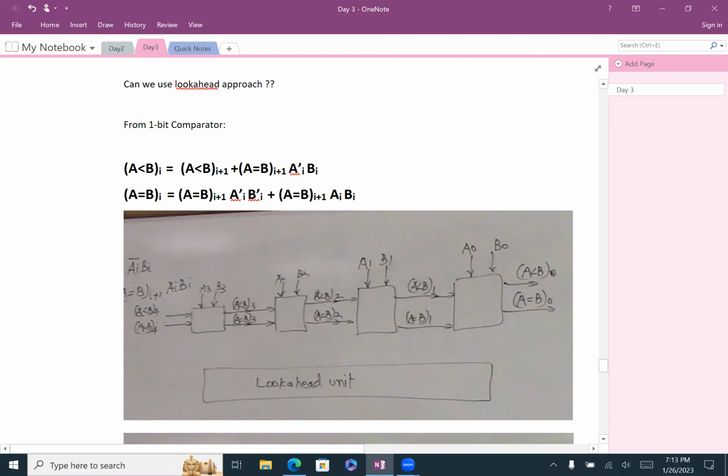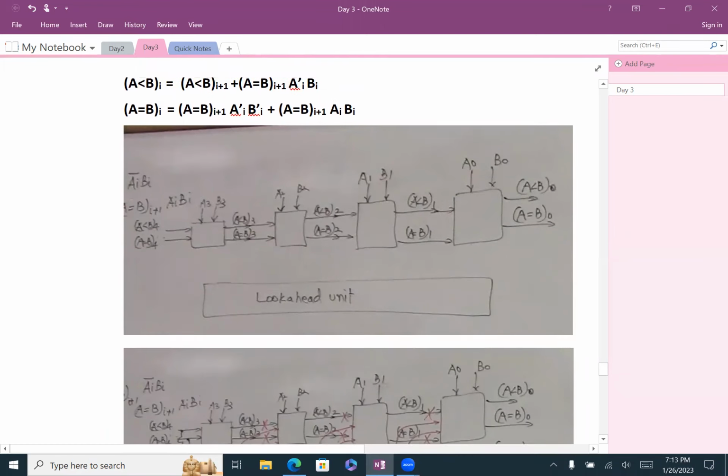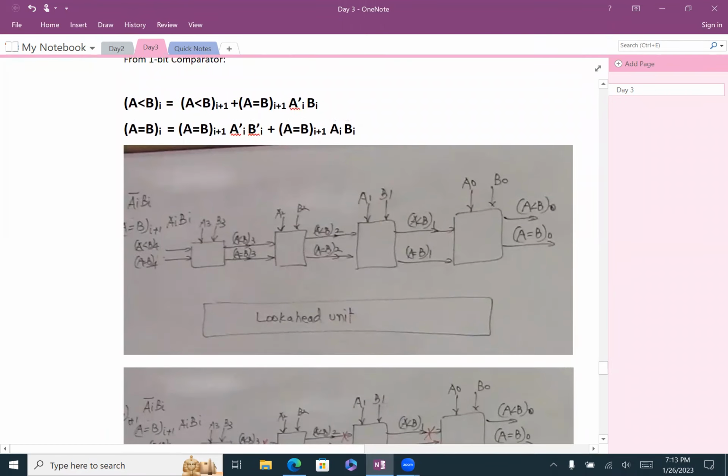When you have a 16-bit comparator, can you use the OR gate? Again, but then you're adding delay. Yes, you can use the OR gate and keep just ORing, but then you will have delay forever. So adding more gates, you're adding more levels, then of course you'll get to the point where you cannot have the right answer. All right.